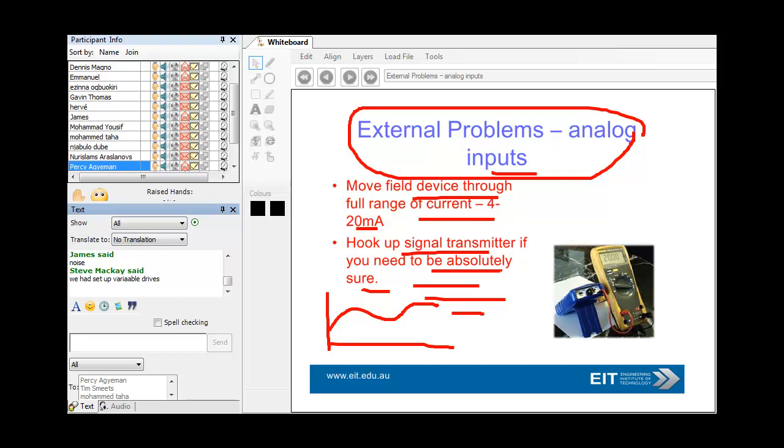What was happening was I was running a little radio station in that MCC, motor control center, and we had harmonics all over the place, coming through the earth, everywhere, from these variable speed drives. I had all these high frequency harmonics on my normal signal, and I had what we call an aliasing problem.